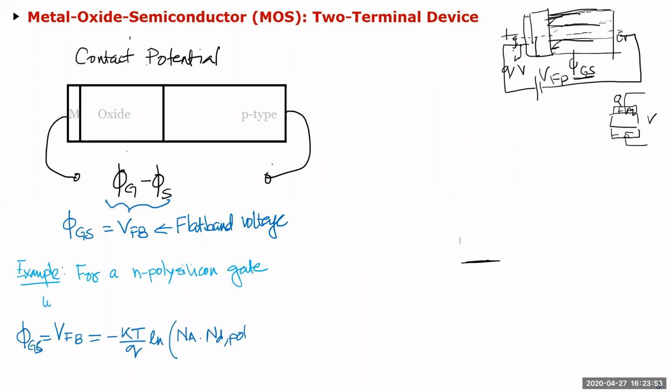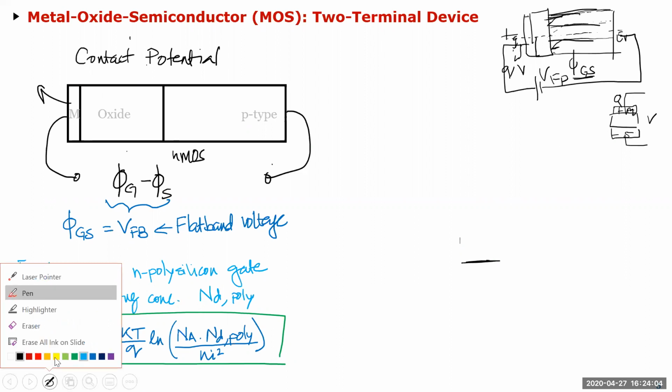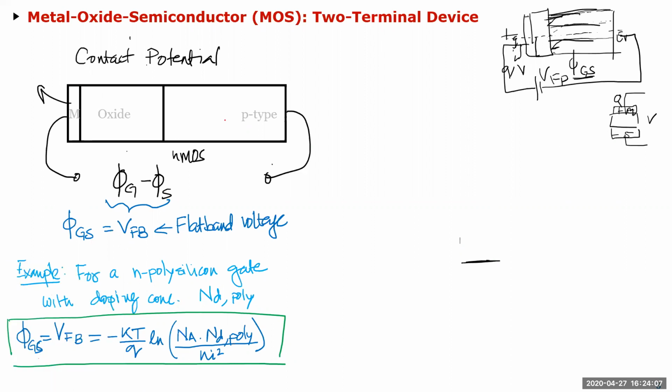Okay, and so if you take an example, for example, an NMOS, in NMOS, this will obviously be a P type or a P minus type material, and this will actually be N plus. Okay, and I'll explain why it is N plus in case of an NMOS and a PMOS. First, I'll probably ask you that question, and then I'll explain that. Okay, so that's a term which is missing from the VT term.